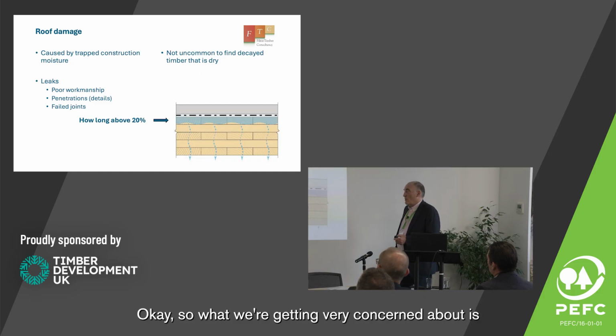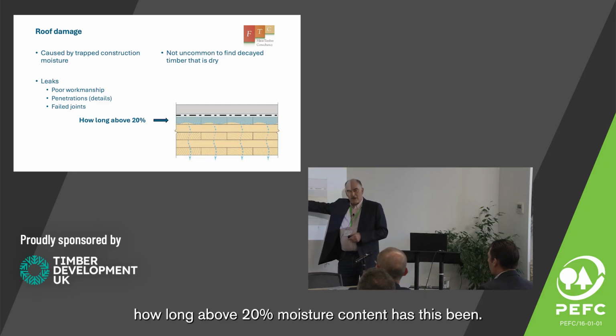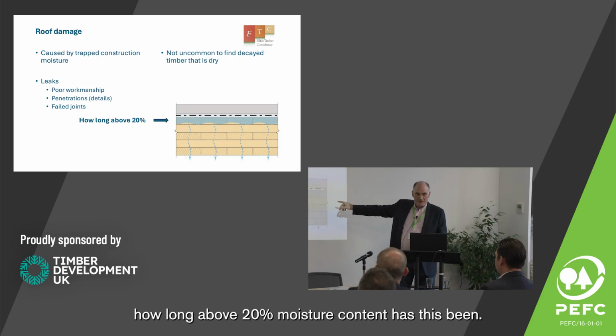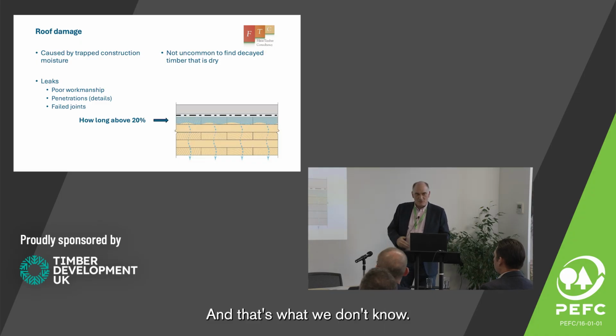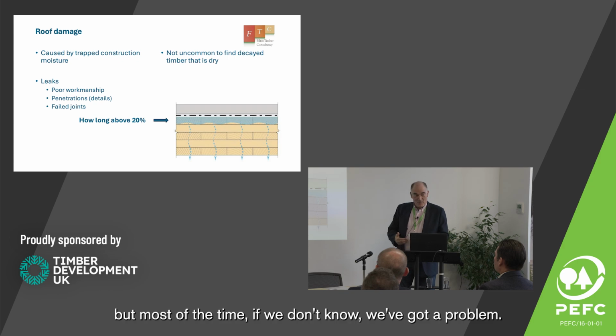Okay, so what we get very concerned about is how long above 20% moisture content has this been. Okay, and that's what we don't know unless we start inspecting buildings. But most of the time we don't know we've got a problem.